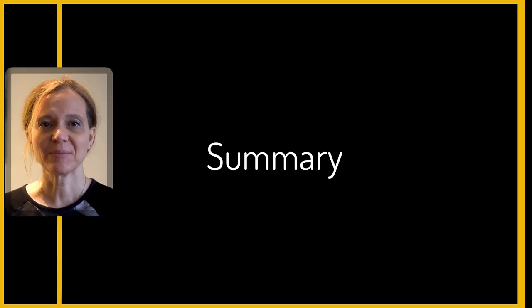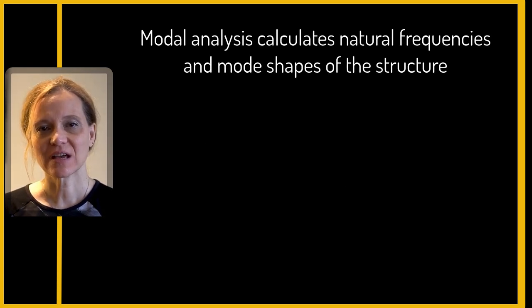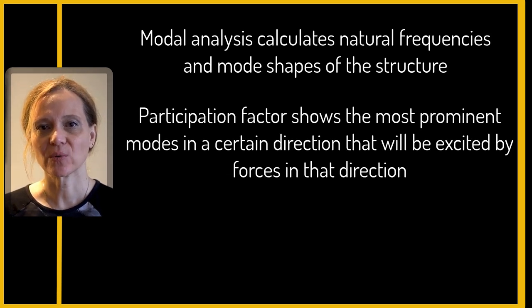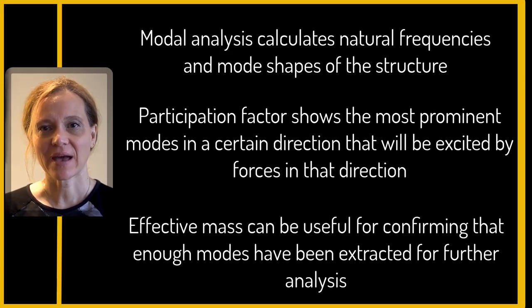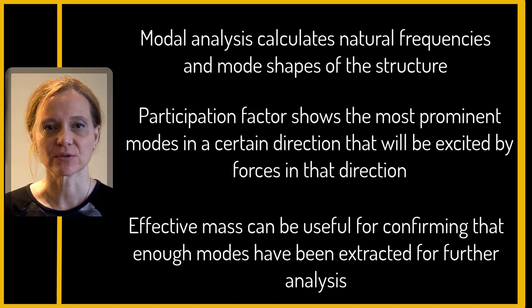This concludes the demo. Now let's summarize what we learned in this video. Modal analysis calculates natural frequencies and mode shapes of the structure. Participation factor shows the most prominent modes in a certain direction that will be excited by forces in that direction. The effective mass can be useful for confirming that enough modes have been extracted for further analysis such as harmonic, response spectrum, or random vibration.